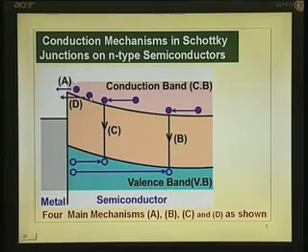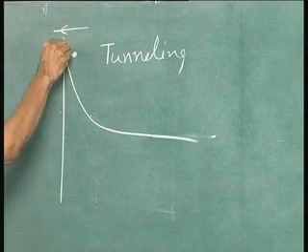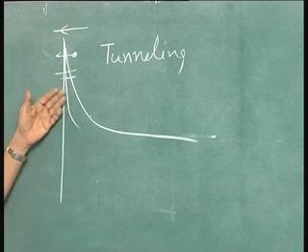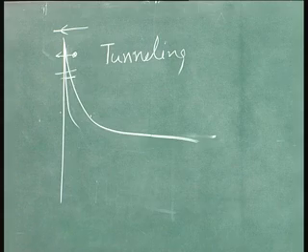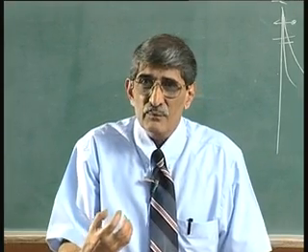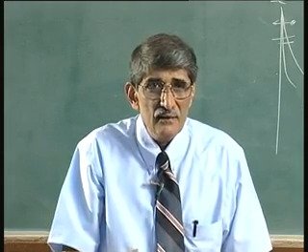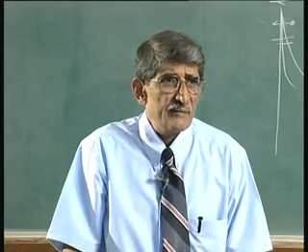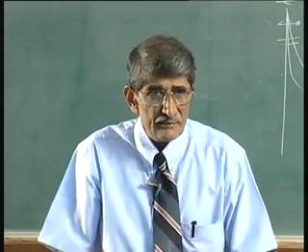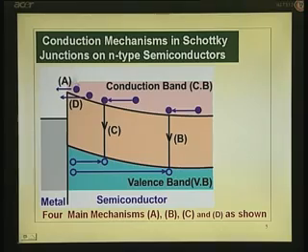For example, you have already seen that if the doping is high, that component becomes very high. If the doping is high, then the entire layer becomes thin, and tunneling becomes very easy. Okay. So, that is an example showing that when you provide a proper condition, other terms will also begin to show up. Otherwise, normally for wide band gap semiconductors like gallium arsenide, silicon carbide, gallium nitride, etc., and even silicon, the main component is A.